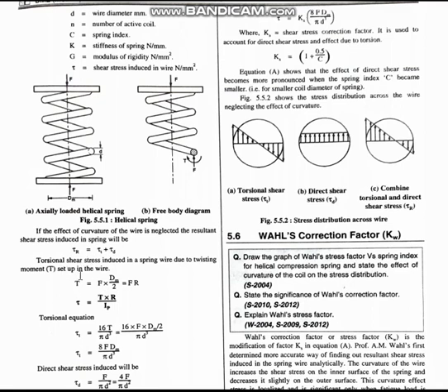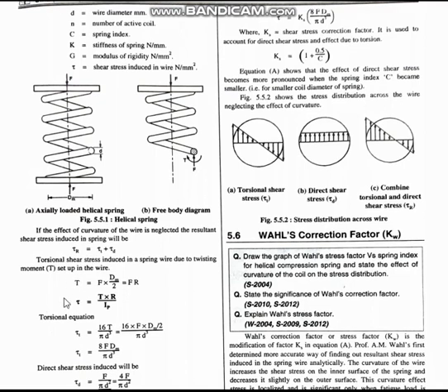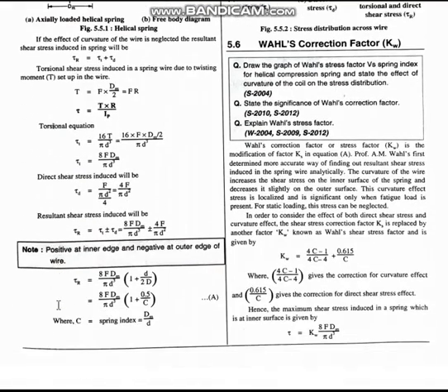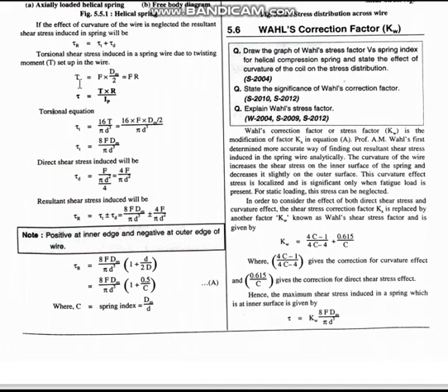Now we have to derive a formula for it. When we are deriving a formula, torque can be given by F into the distance at which this force is acting. F is the actual force and the distance at which it is acting is the radius. Radius is nothing but mean diameter by 2. That means F into R is F into D by 2. We will not be solving all this using radius; we use diameter only because handling the diameters is easy.